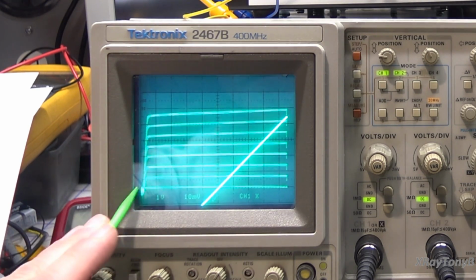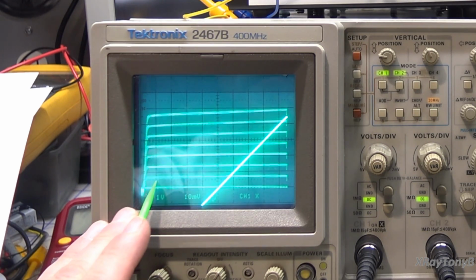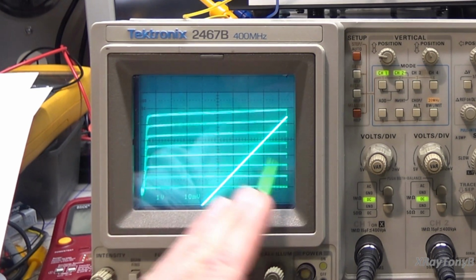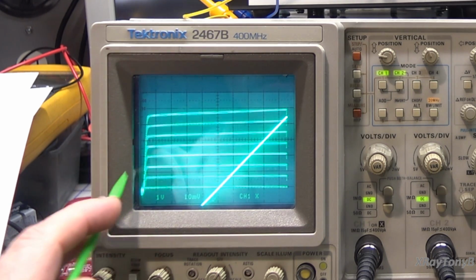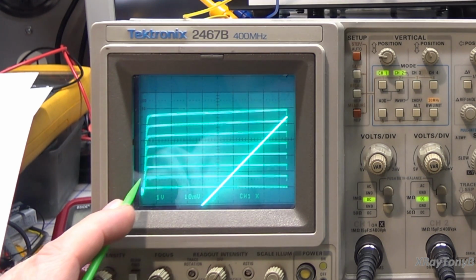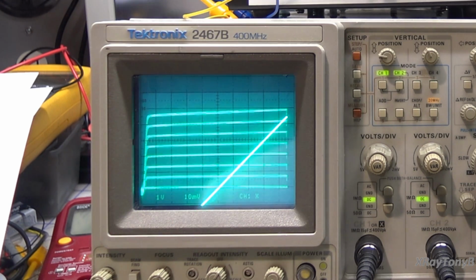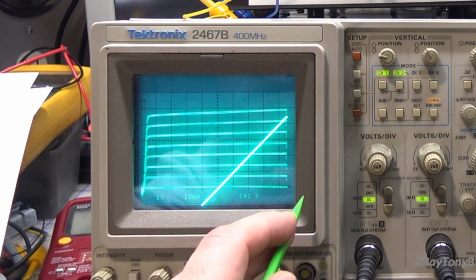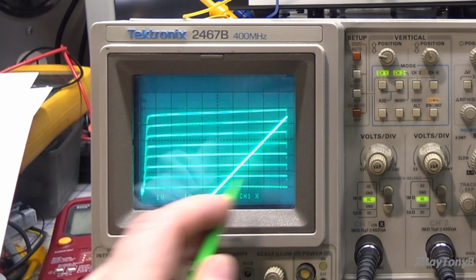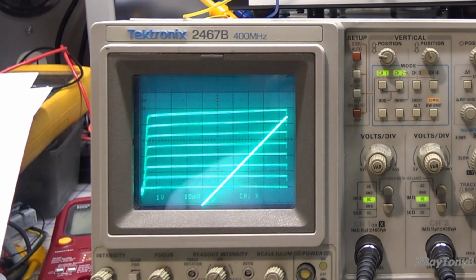And what we're looking at is each one of these lines represents a certain base current that's being applied from the base to the emitter. So it would be IBE, current from the base to the emitter. And for each base current, we're sweeping with a sweep signal from 0 volts up to just a little bit under 10 volts.